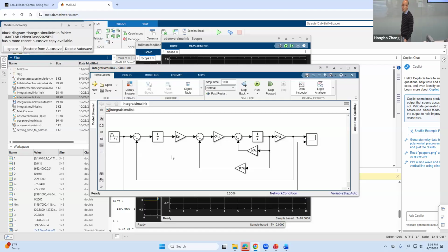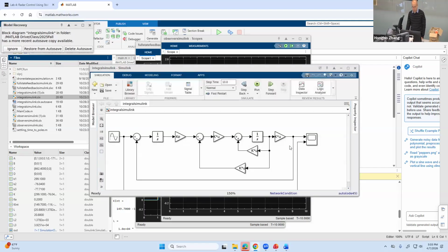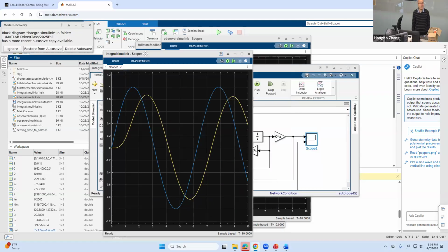With integral control, you can actually see this state space becomes very... Look here. Oh man, look at that. Is that great? The error is not much anymore. Almost none, right? You see? The state space with integral control removes the steady state error, which exists for full feedback control. Make sense, guys? Does the error make sense here? Is it clear? I think it's pretty interesting.